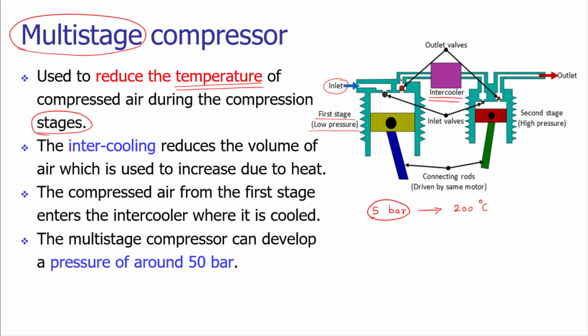The compressed fluid will be sent to the intercooler. The intercooler is nothing but a heat exchanger. This heat exchanger has an outside supply of cool fluid. It may be cold air or cold water which is circulating in the intercooler, which will reduce the temperature of the compressed air.